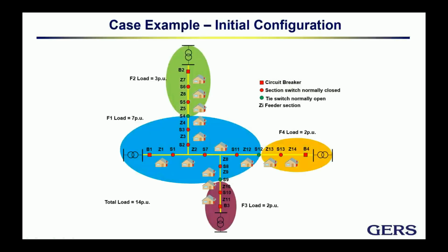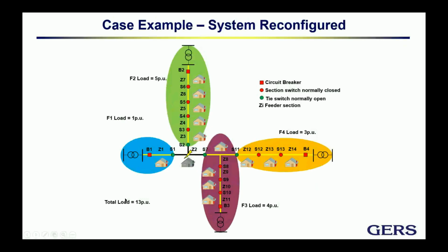However, let's go into the protection system. The protection system was operating as indicated here. I already told you. Feeder 1 had 14 sections, feeder 2 had 3 sections, feeder 3 had 2 sections, and likewise feeder 4. But during the downstream restoration, guess what? Well, feeder 1, of course, went from 14 to 1. Perfect, no overload. But feeder 2 went from 3 to 5. Feeder 3 went from 2 to 4, that's twice as much. And feeder 4 went from 2 to 3.